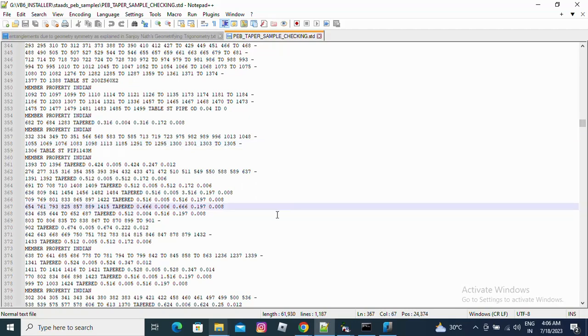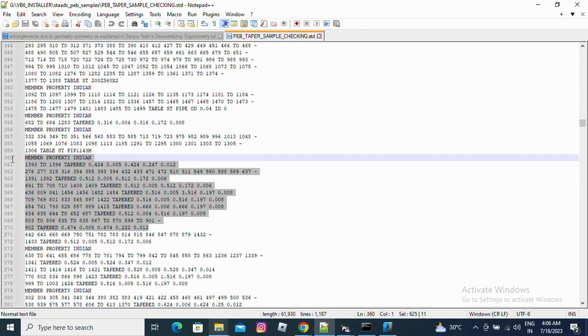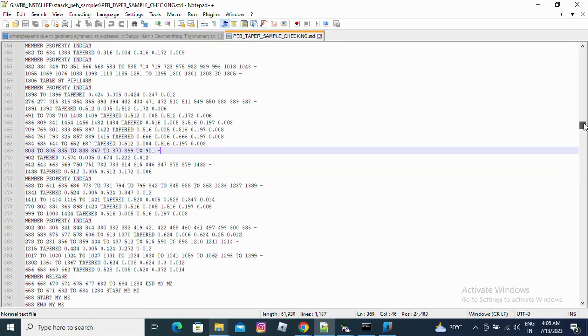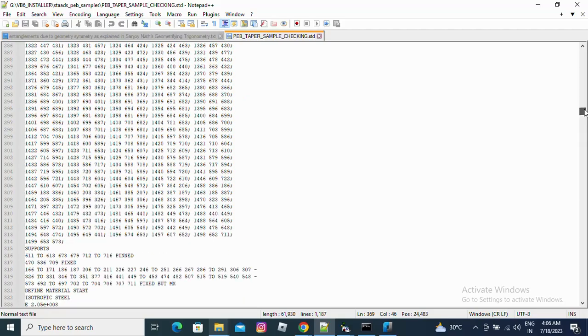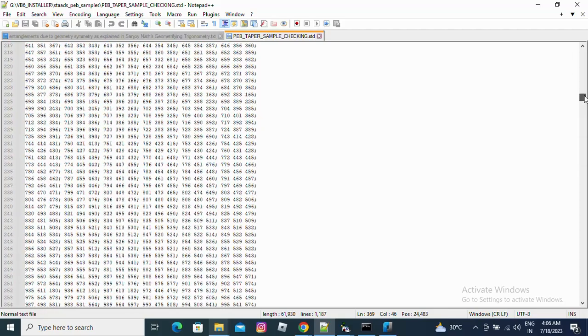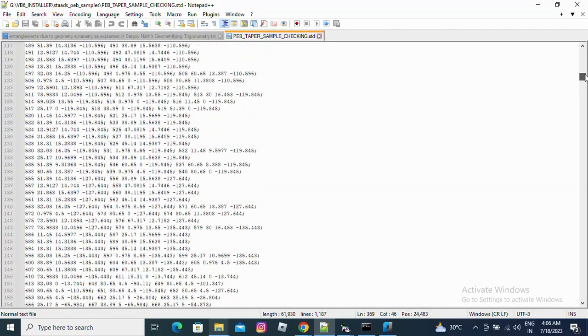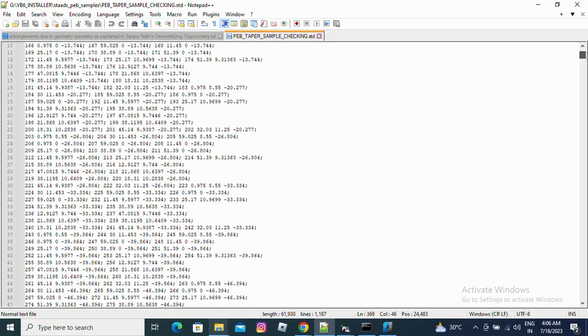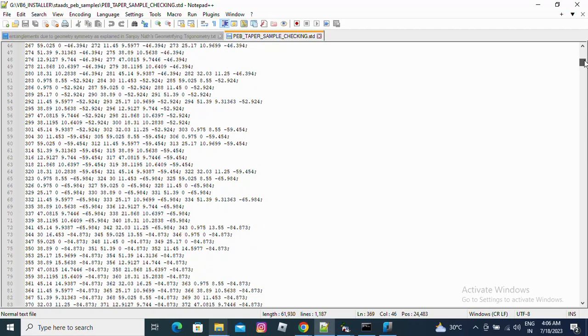Our Indian PEB companies convert those to tapers or plated models while they fabricate the objects, because of the 240 MPa or 345 MPa issues. The availability of plates is greater in the Indian PEB sector. So whatever the design conditions used, people prefer to convert everything to plated structures. That is the big pain area in our Indian pre-engineered building structures.